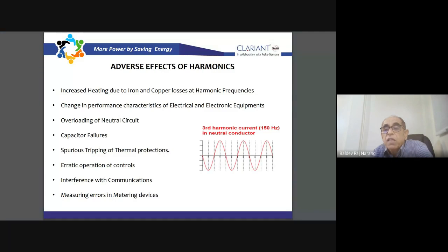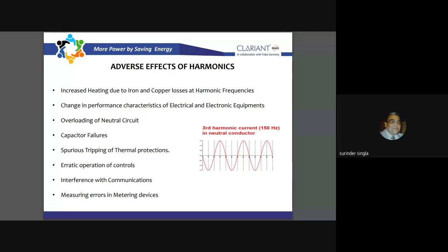The single phase loads create the unbalance, or it could be for any other reason. Suppose you have unbalance, it will create third harmonics. If already, because of the unbalancing of load, some neutral voltage is persisting in the neutral, and then the harmonics come, is there a multiplying factor, or is it a straight line increase? Is there any study on this?